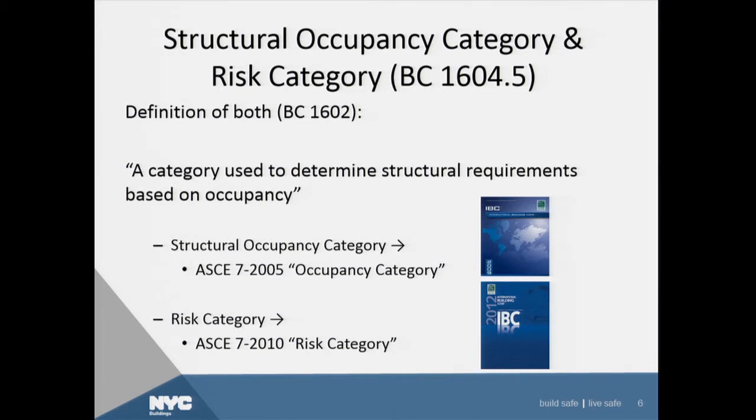We're undergoing a slight change in terminology as far as structural design is concerned. As part of the 2008 Code, we adopted a term called the Structural Occupancy Category, which is used in ASCE 7-05 and earlier. They actually call it Occupancy Category. We added structural to it here in New York to distinguish it from occupancy classification, because we can't have terms that sound that similar. We'll be talking about the wrong requirements if we're mixing up those two terms.